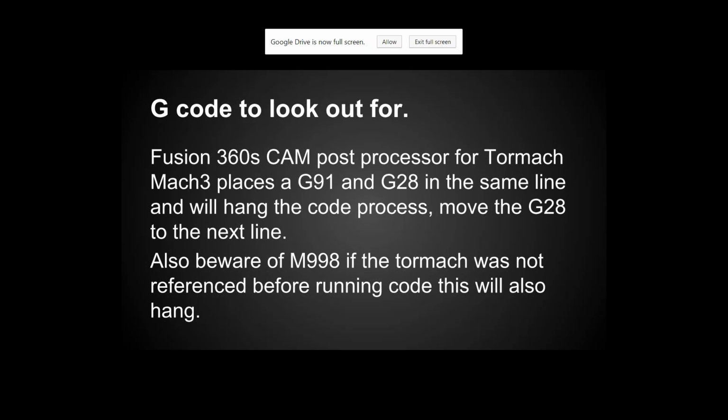If you're changing the orientation of the stock, do you change the tool path? Typically, what you'd have to do is design, like right now you have the CAM up for right there. If you wanted to machine that, you'd bore out the one hole, do the flip. Now, for the CAM for the next orientation, you have a copy of that part in your file, you'd have to design in your jig plate into the file with the part. Essentially, you'd have another copy of that body at 90 degrees, at the correct orientation. So you'd machine a block there. That way you would only have to have one tool change for two parts essentially.